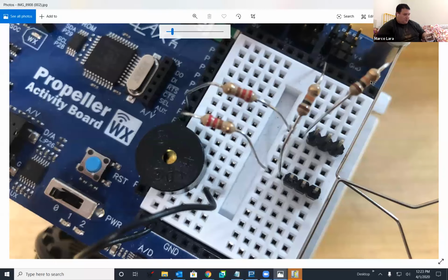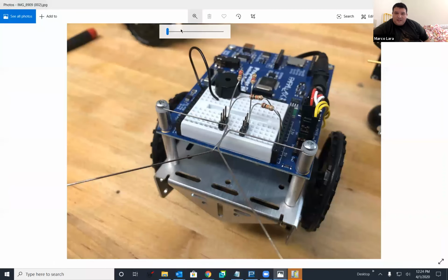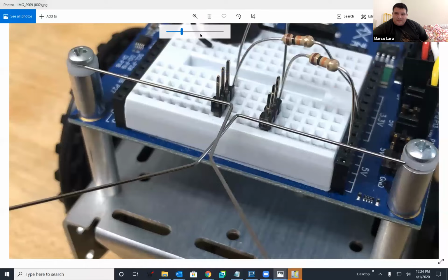All right. So yeah, those are the changes. Took those 2 other resistors out and then made sure that these 4 resistors now have more space between each other. Also, looking at Ken's diagram, do you see where Ken's mouse is right now? See how that resistor is getting really close to the whisker? That's another gotcha: if you're pushing on the whisker and it touches the resistor lead, that would be another way to get a phantom positive reading. Or actually, I think that would force it to be a did not detect reading. Well, I'm not even sure. The picture you just had up is different than what's in the tutorial.